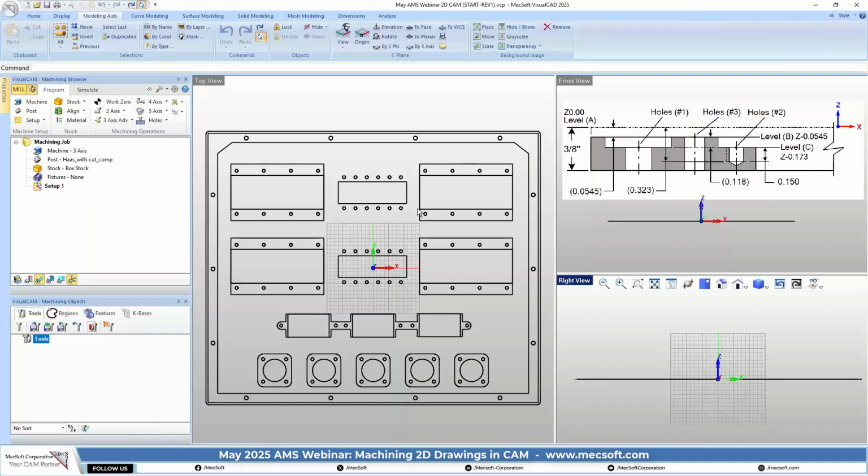In 5-axis, you need either a surface or a mesh similar to 4-axis. It's a little bit more to understand in 5-axis, because if you do continuous in the index 5-axis where you're rotating in planes, that will revert back to the requirements of whatever you put in that indexed fixed orientation. Drilling, 3-axis, revert back to those requirements.